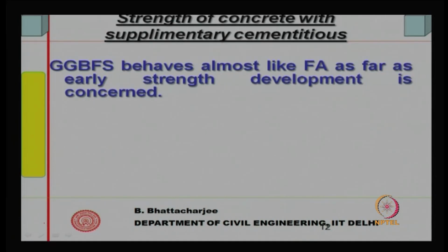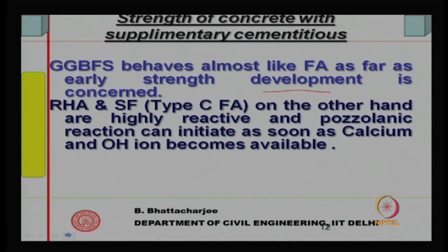activation of GGBS will require cement, dissolution of the cement material, and it does not start really early, and the pozzolanic advantages also come much later once sufficient lime has been produced. So, the pozzolanic benefit is obtained later. Therefore, early strength development is not very much as far as GGBFS is concerned.